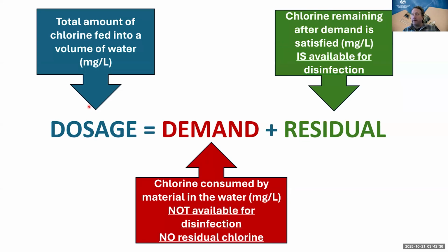Again, the units are milligram per liter. It is available for disinfection. So remember that dosage equals demand plus residual. Whatever you feed into the water, what's used up, what's left over to keep disinfecting.